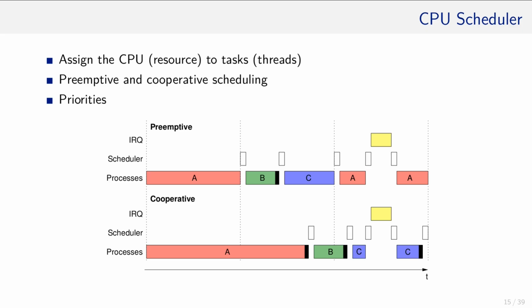This time, the tasks which hold the CPU resource get as much time as they want to complete. The scheduler does not interrupt the tasks with one exception, and that is if the tasks are disturbed by a high priority task such as an interrupt. Now it is the responsibility of the tasks to tell the scheduler that it may consider another task to be scheduled now.